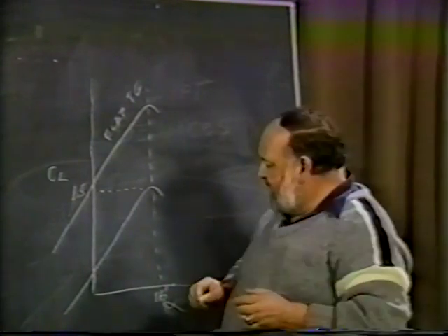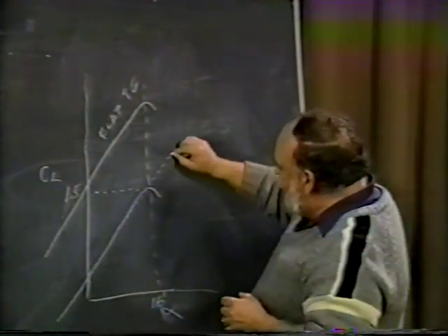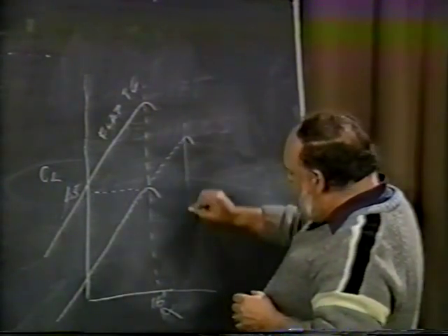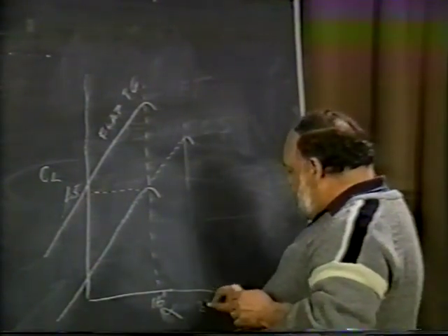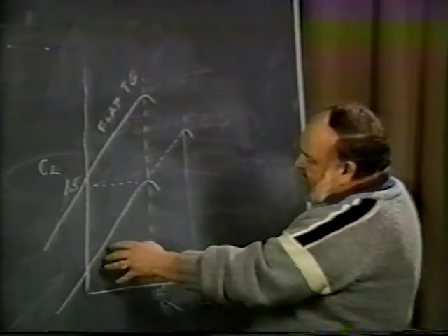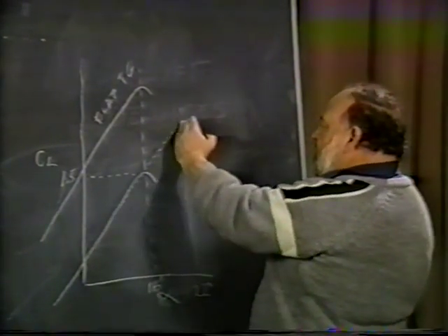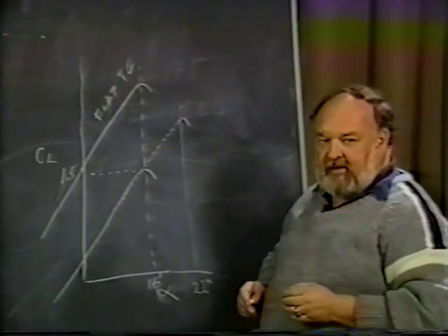The leading edge, on the other hand, assuming you don't have flaps on it, will take this original curve and extend it to maybe 22 degrees angle of attack. So without flaps in the back, if you put a leading edge extension, you're going to take the standard lift curve slope and just continue it on to a much, much higher angle of attack.